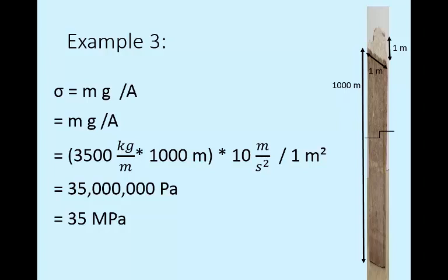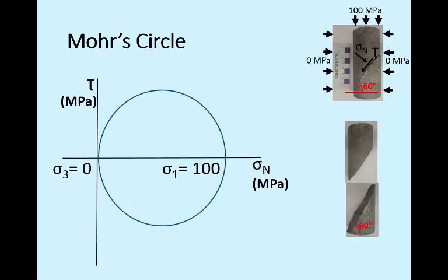So how do we know that there is stress? It could be signs like if we drill a hole and it was originally round, over time it might become oval, or we can see tunnels changing in shape. Because geological factors affect rock at depth, a rock mechanics engineer must be able to estimate stresses in different orientations.